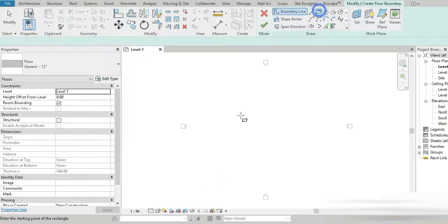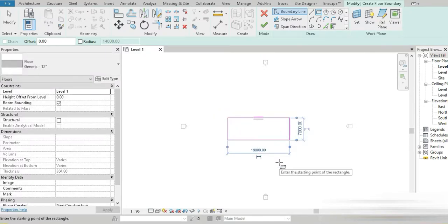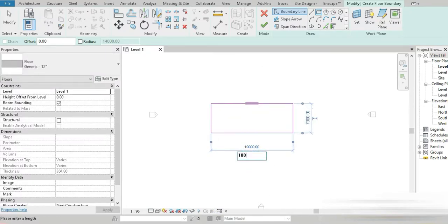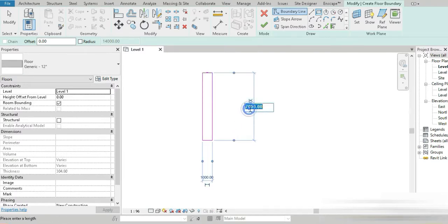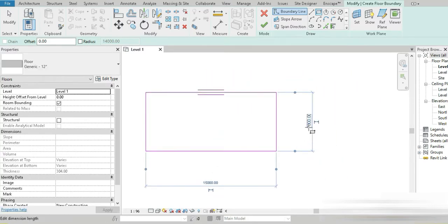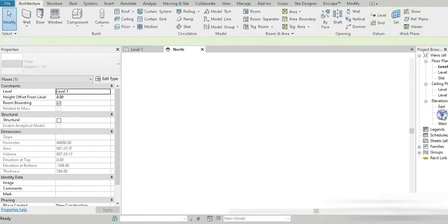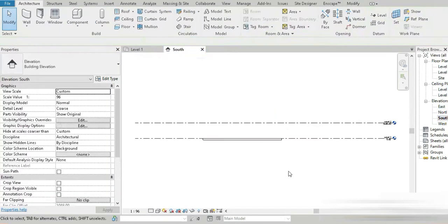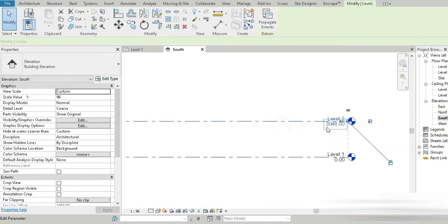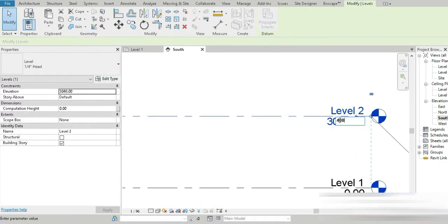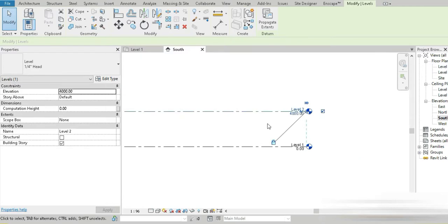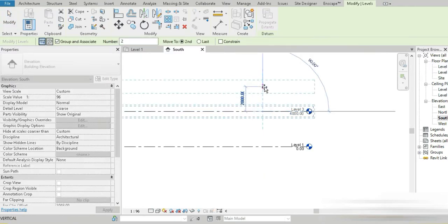All right, let's grab a rectangle and let's just paste it. No big deal. So let's set the size to 10,000 by 10,000. 10 meters is so small. 15,000, it's in millimeters, right? And 15,000, and this one we can even make it 5,000, right? No big deal. So okay, now that is pasted, let's quickly go to the south, not north, the south. In fact, it's the same thing. So let's grab on that. Let's change this to 4,000. It means 4 meters. Now let's press AR and let's rise it above.